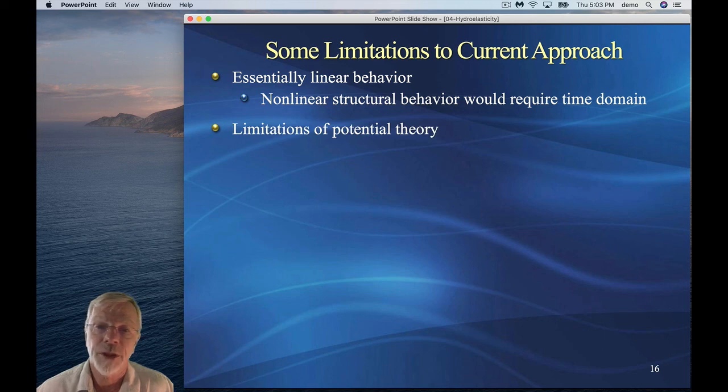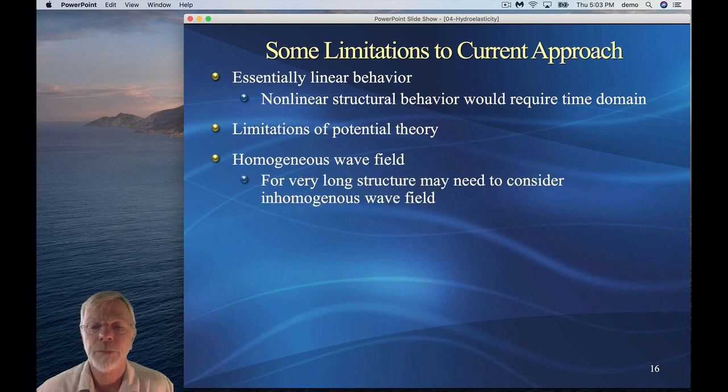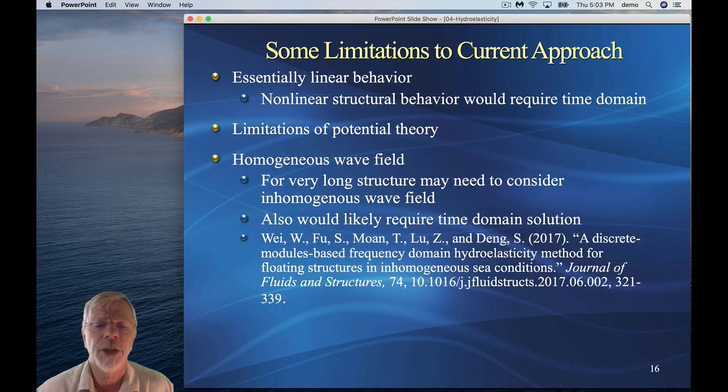We obviously are subject to the limitations of potential theory, and we also have the limitation of a homogeneous wave field. So for very long structures, we may need to consider an inhomogeneous wave field, and I would like to highlight this reference here as one example of that, and this would also likely require a time domain simulation.